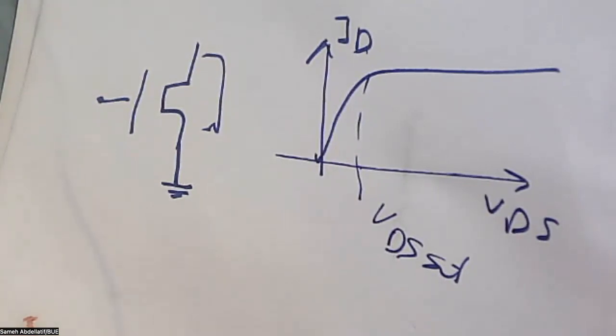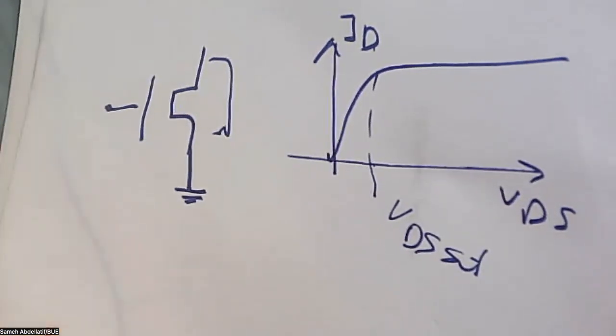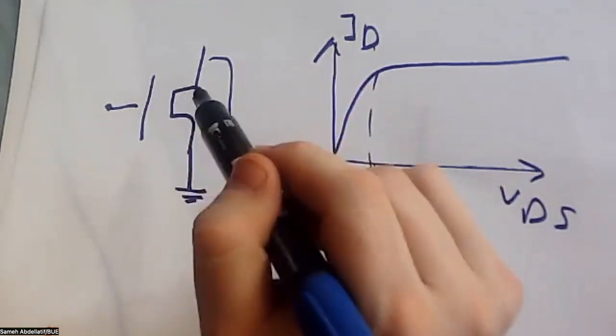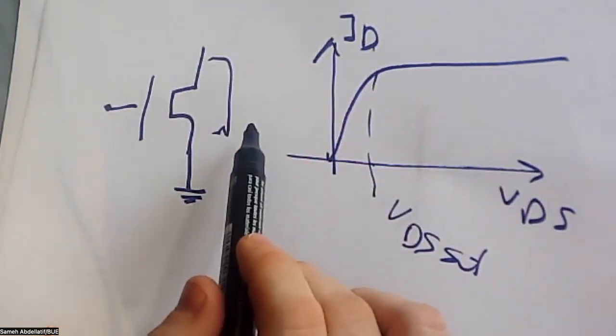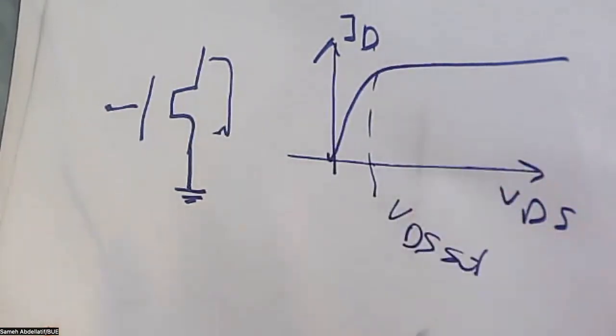However, the key important point here, my dear students, is that during this experiment, you are going to fix the operating point of the transistor. Your operating biasing condition, I mean the voltage applied to the gate or the voltage applied to the drain, will be fixed throughout the experiment. The change that will occur in the current is mainly due to the change that occurs in the semiconductor itself due to the interaction with lactate. That's why it will lead to a change in current.